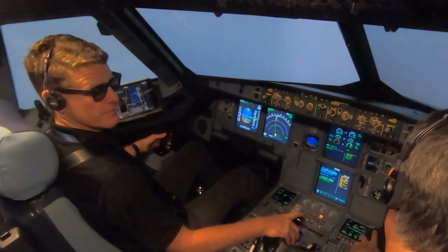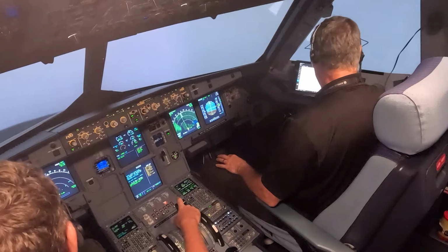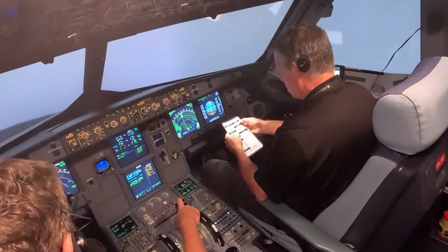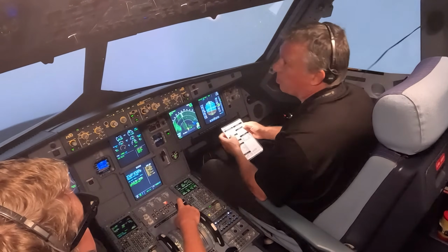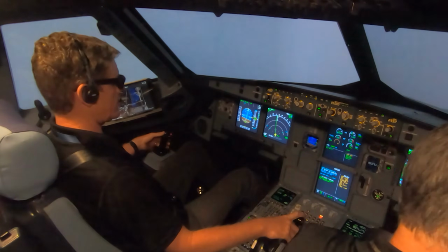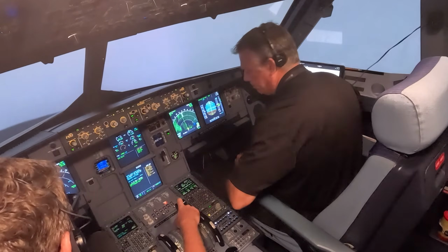The after takeoff flow has been accomplished. I agree. After takeoff checklist. Take up checklist. Takeoff checklist is complete. Over, we have the APU running. Thank you. There's no system resets, and an engine relight is not applicable. Not here. Continue ECAM.